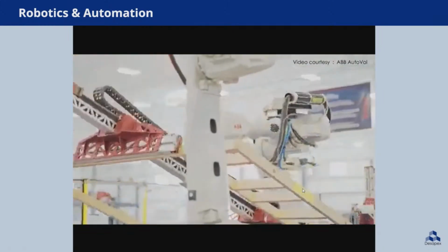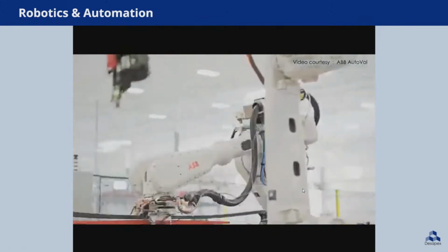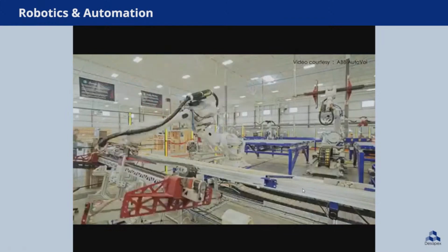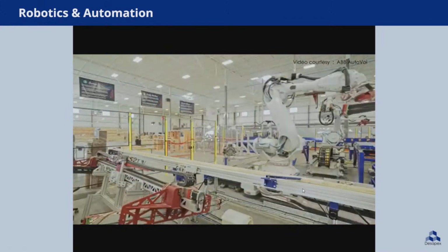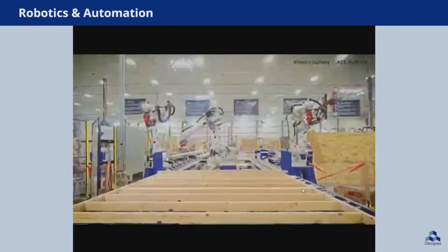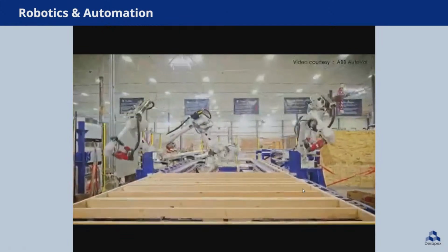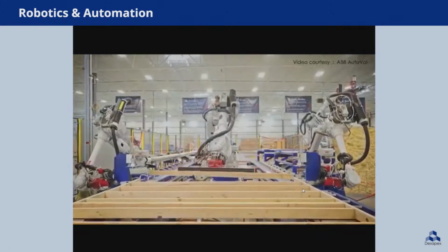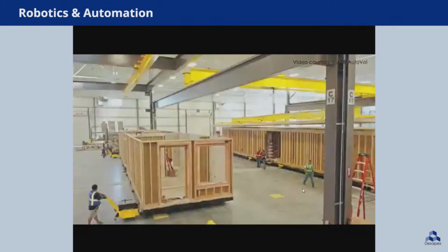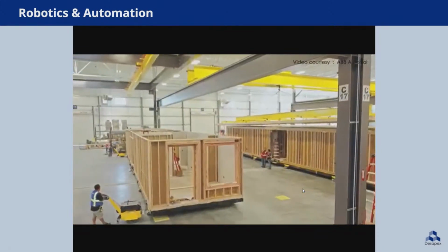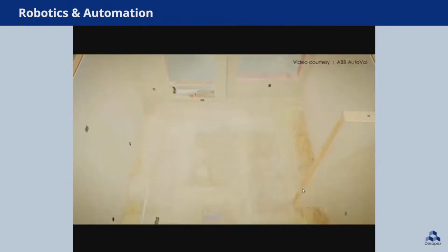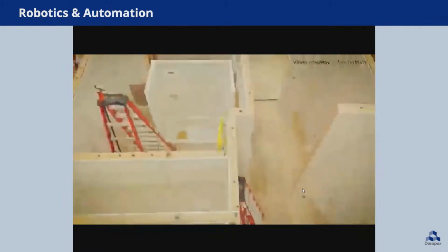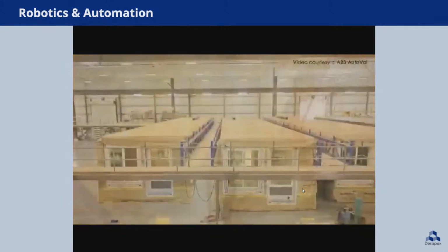The robots produce timber components according to designs created in the Intelligent Cities Platform for Life, that is P4L's design software, enabling customized structures for the built environment. Here, the RobotStudio offline programming software is also used along with P4L to plan tasks and movement for the robots, where every component gets its own file and can be simulated and exactly directed.